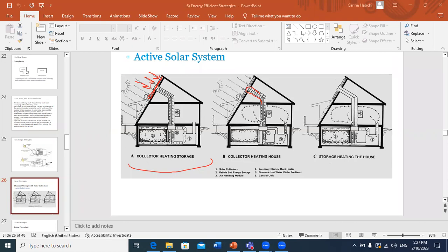So you circulate your water by means of a pump, and then it will go through the heat exchanger within the solar panel. It will be heated by the solar rays, so it will transport the solar energy collected at the level of the panels. And now you will distribute this heat in case you need it now. Of course, a part can be taken to a reservoir that can be used to supply domestic hot water needs, let's say shower, or use of water in the kitchen, etc.